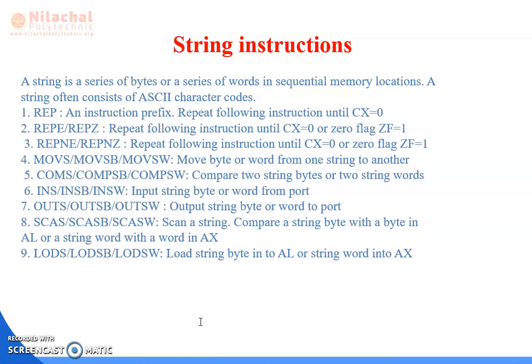So next is string instruction. A string is a series of bytes or a series of words in sequential memory locations. A string often consists of ASCII character codes. So first one is REP, that is repeat. An instruction prefix: repeat following instruction until CX equals 0.